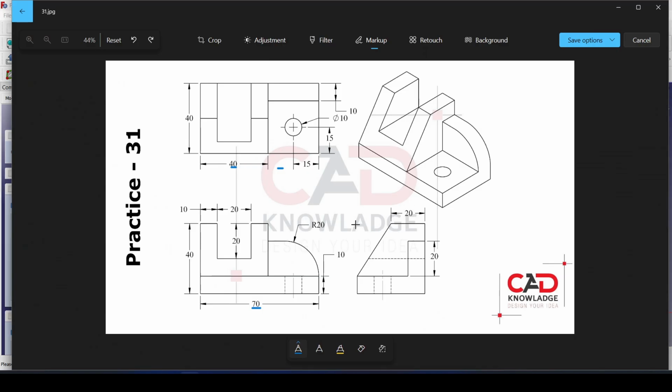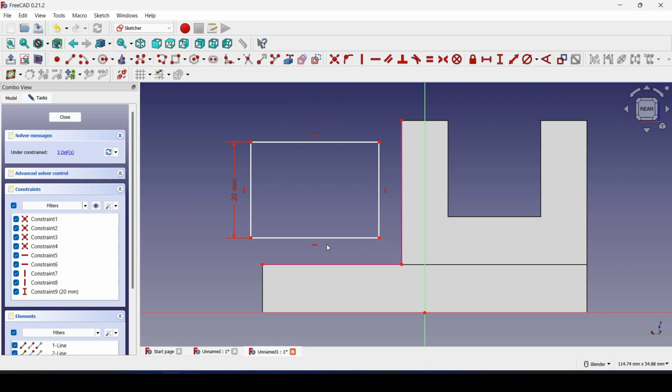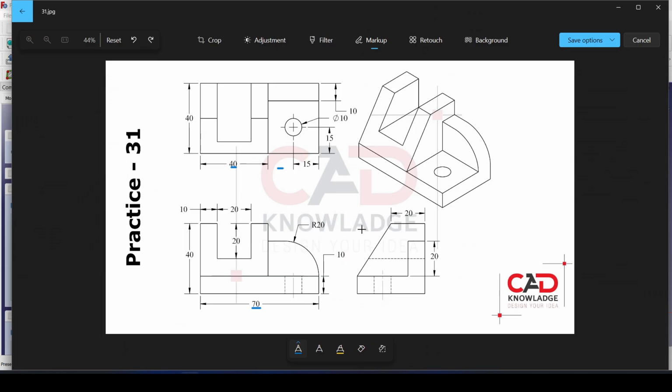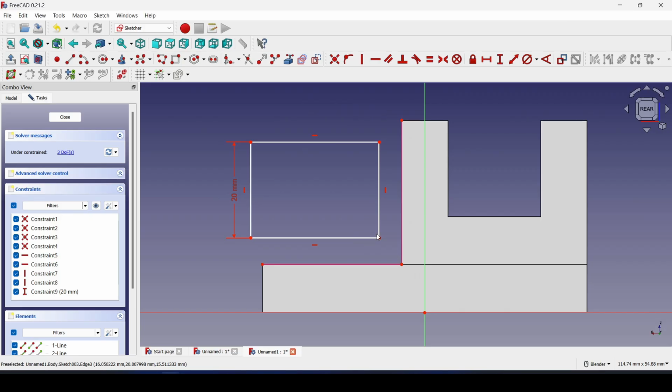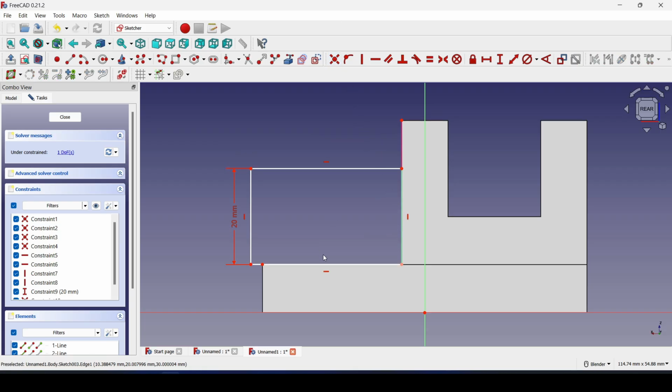And instead of hard coding any sort of horizontal distance, because I don't think the sketch really tells us exactly how long it is, what we do know is that our bottom corner meets here. So I will take this point and use the coincident constraint and join it to this point. Oops, click that again, okay.